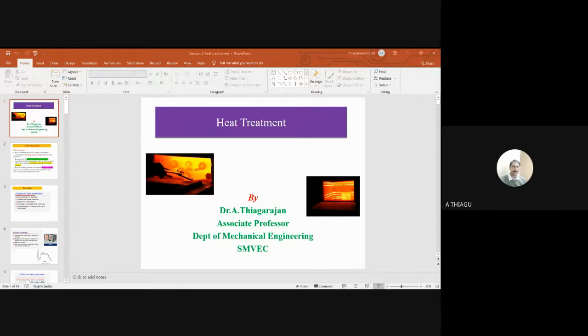So these are the various processes we have covered. For carburizing, the suitable temperature will be 900. Carbon should be deposited. Application-wise, steels, alloy steels, mild steels are the major applications, and hardness will be increased. Okay, for carbonitriding, we have to mix at temperatures of 800 to 850. Most of the applications come under alloy-based steels only.